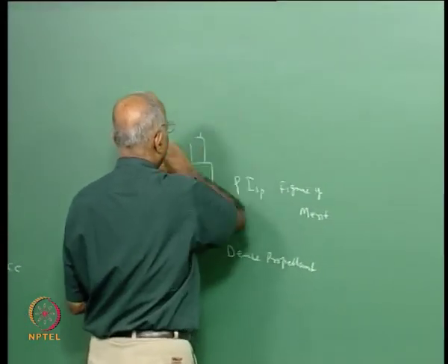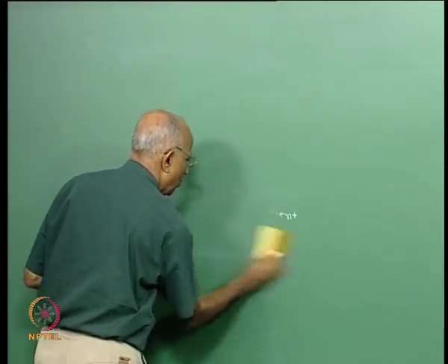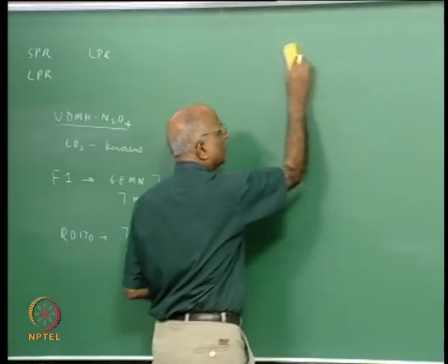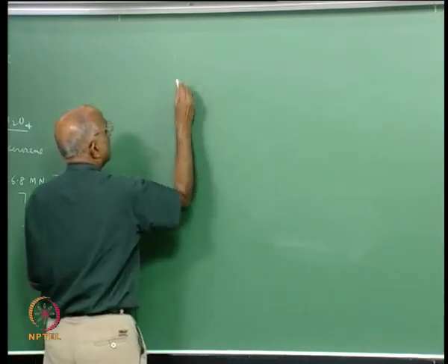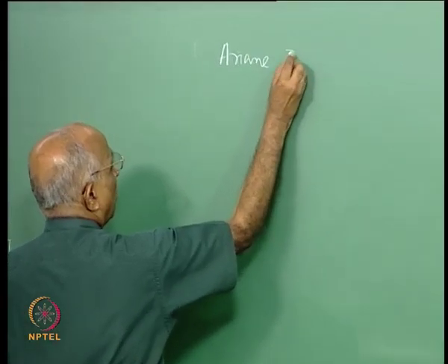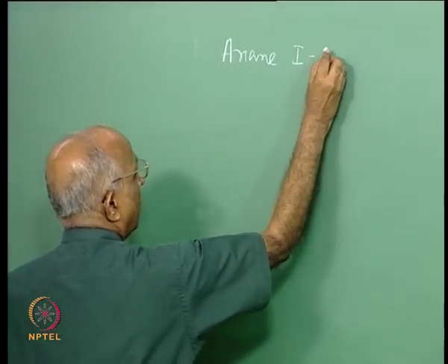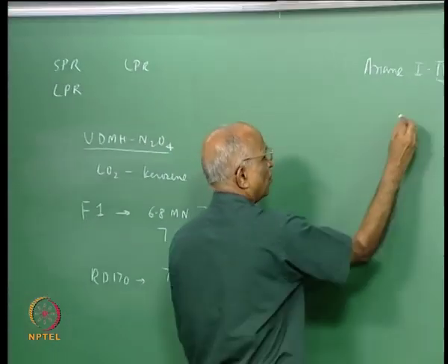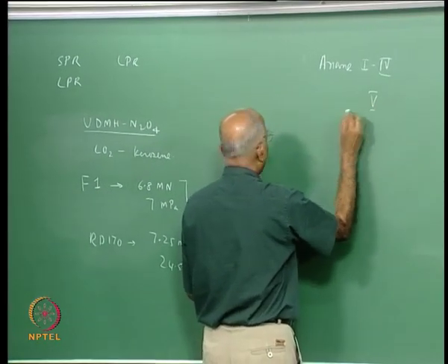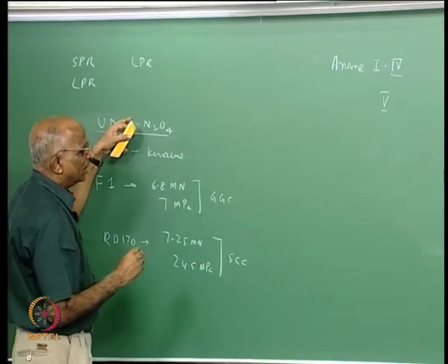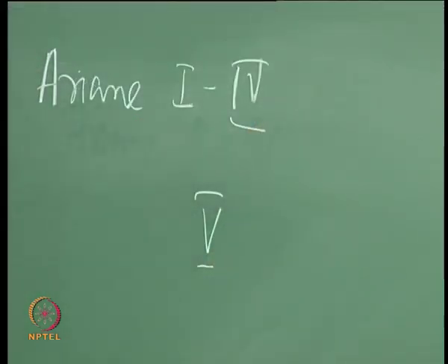for boosters. But ever since we were told that UDMH is cancer causing, it is also costly, the trend is not to use UDMH, and therefore presently the Ariane rockets, like let us say Ariane rockets 1 to 4, they make use of UDMH N2O4, but the more recent one, Ariane 5, does not make use of UDMH N2O4. But what we use is a derivative of what was used in Ariane.